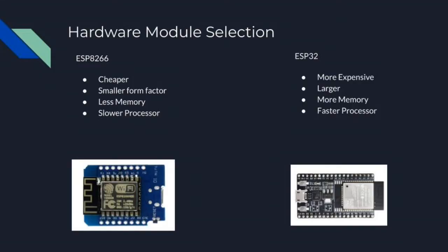When it came to choosing a hardware module in this IoT space, we had many constraints that we needed to consider, but the most important and determining factors were that the board needed to be easily programmable, have a suitable number of pins for use, and these pins needed to be able to interface with the common protocols, such as SPI, I2C, and UART. This led us to the ESP family of boards, and two members of this family specifically, the ESP8266 and the ESP32.